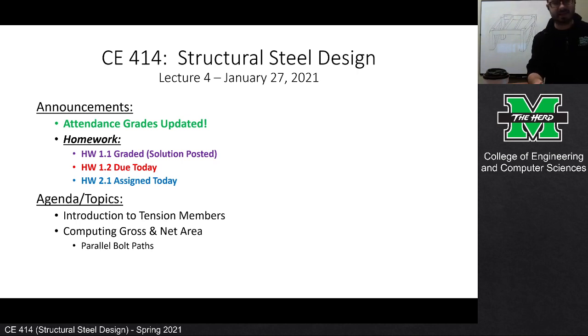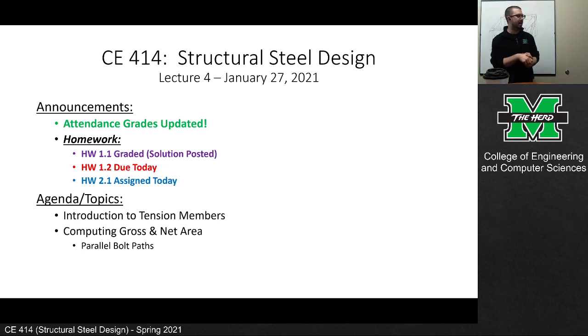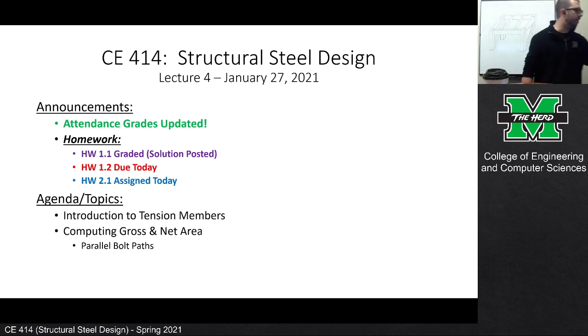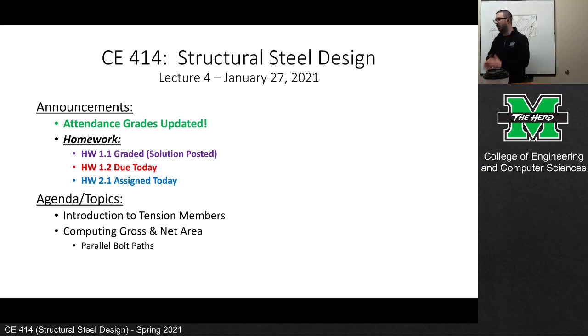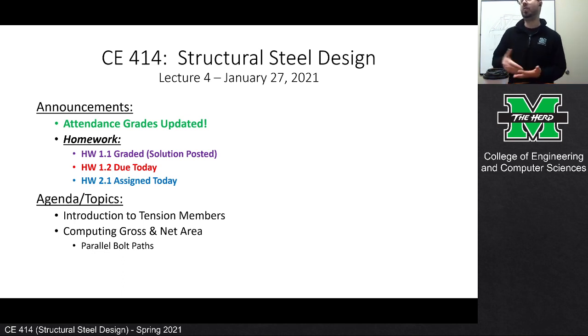So everybody, welcome back to Steel Design. I've got the first homework graded. Everybody did pretty well. The one comment I would mention on the homework assignment, and when you're doing factored loads, there are a series of load combinations that you go through, but ultimately what you want is the factored load, the one that governs. So there were a number of you that went through all of them, but what you want is the answer. Like if I'm designing this beam, what do I design for? And there's 7 different load combinations, but you want the one that governs.